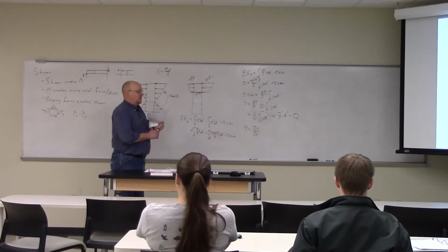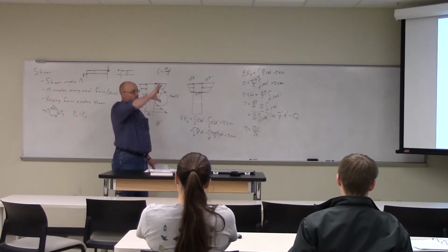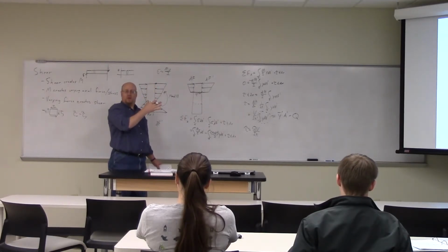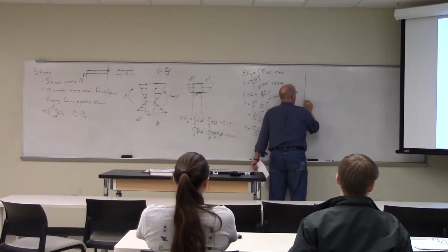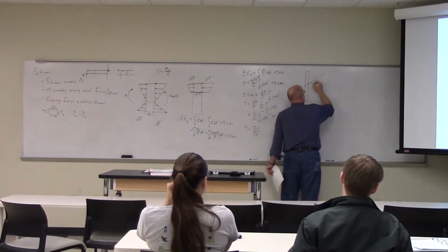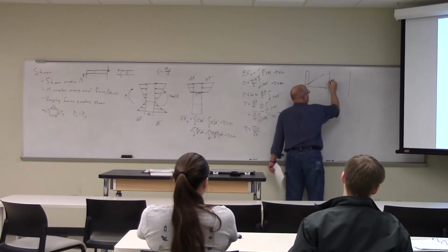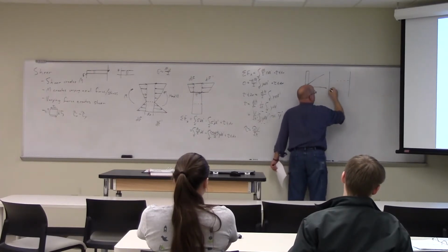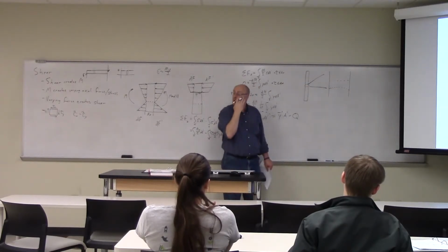And the thicker the part, the wider T becomes, particularly in relationship to the total height of the beam, the more that it varies with the depth. So in other words, if I've got a beam that's really skinny, and I zoom in on the shear stress distribution there, the shear stress distribution might only curve a little bit.